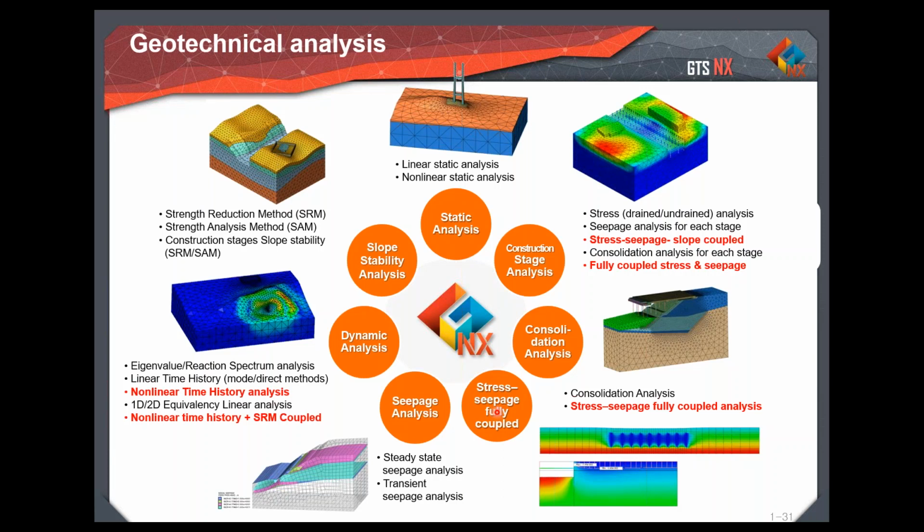In order to consider that in the finite element method, we need to run a fully coupled analysis or a semi-coupled analysis. This is your semi-coupled analysis, the stress seepage analysis. Basically, in the first stage we run a seepage analysis, so we will know the variation in pore water pressure with respect to time if it is a transient analysis. Once we get those results, we apply them in the second stage, where we run a stress analysis and a slope stability analysis. So you're considering your pore pressure variation with respect to time and applying it in the second stage, where you're running a slope stability or stress analysis. So you're considering the effect of your seepage.